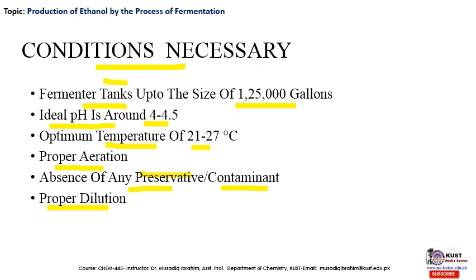If you are using a fed batch method, the dilution should be carried out by taking out the amount of the culture which has developed in the same amount of quantity as the amount of nutrients being added to the fermentation tank.